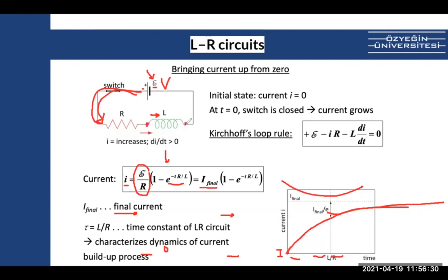Voltage on this inductor becomes 0. Why does this become 0? Because this inductor now has no change of current. Right? So what is the equation? L di over dt equals VL.